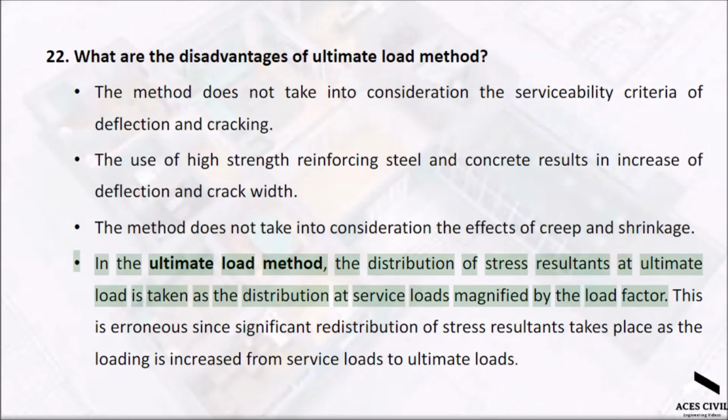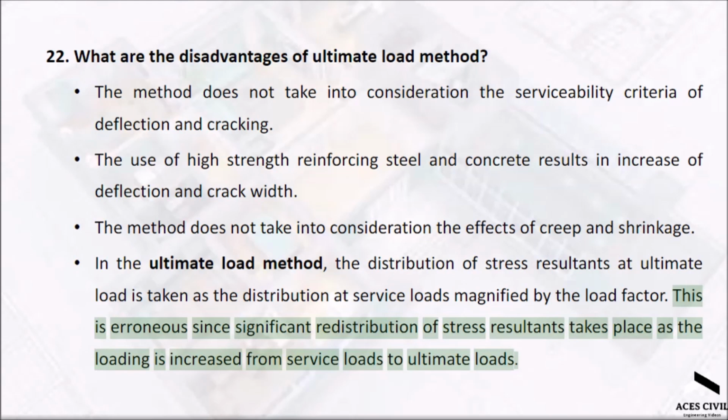In the ultimate load method, the distribution of stress resultants at ultimate load is taken as the distribution at service loads magnified by the load factor. This is erroneous since significant redistribution of stress resultants takes place as the loading is increased from service loads to ultimate loads.